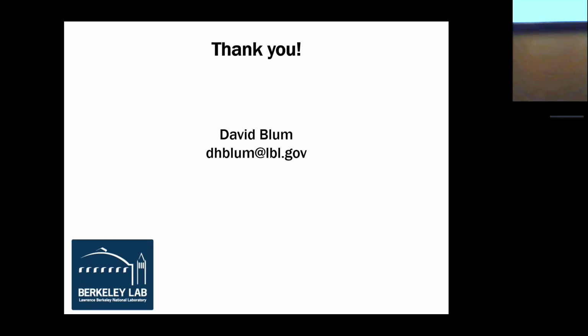It turns out they're difficult to simulate within the Modelica model computationally efficiently. So that's something maybe I can discuss with some of the folks here. For instance, simulating noise within the Modelica model causes events, and that really slows down simulation time. Yeah, there are some computational efficiency issues that we have to think about. So if people have good ideas, we're all ears as well.